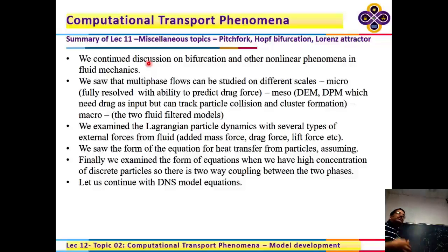So essentially what you're doing in this case is giving it a profile that has very similar differences in the centrifugal force. In some region the flow is going out, in the other region it is coming in. That would be a good initial guess. Starting from that, you will find that it will converge in fewer iterations than 1,000 or 2,000 or so. So to promote convergence, you can do something like this.